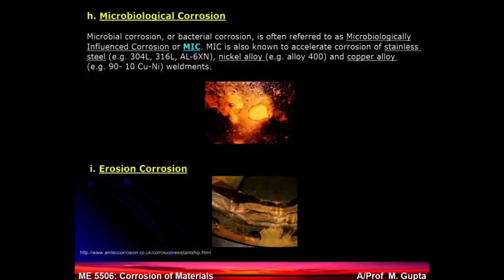We discussed that before. You can also have microbiological corrosion. Some people call it microbiologically induced corrosion, MIC. So don't get worried about this word MIC. It's the same thing. Here you have sulfate reducing bacteria which can attach and start creating pits. And since seawater has a lot of sand particles and all these things, you can also expect erosion corrosion to happen.